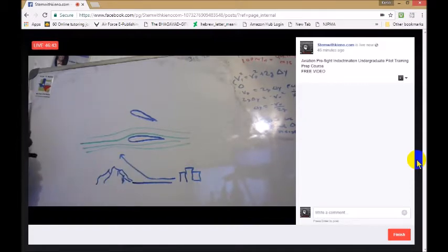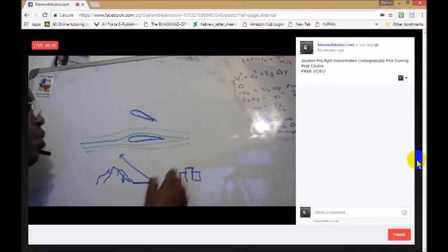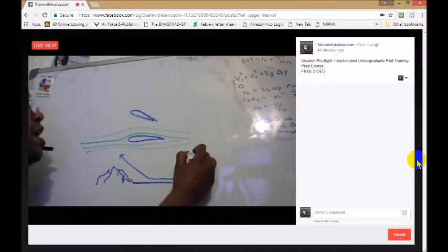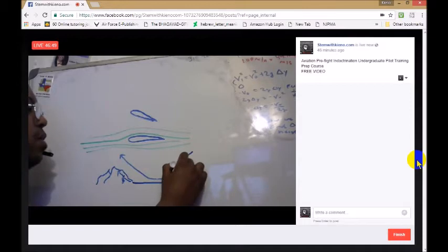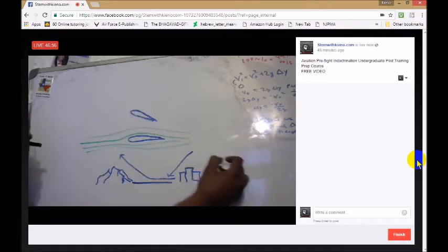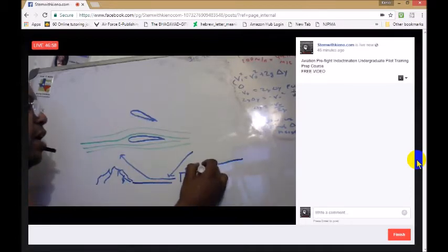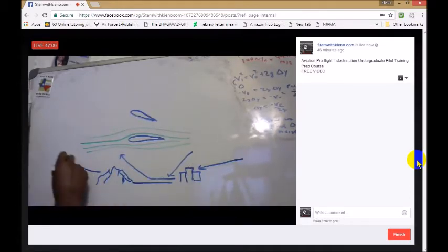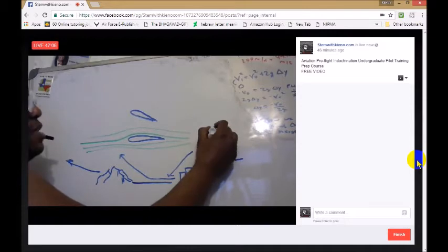Conversely, if we have obstacles at the approach end of the runway, we can come in at a steeper glide path without increasing our airspeed. So if we didn't have slats and flaps, we would need more of a takeoff and departure or approach and departure path like this. But when we extend our flaps and slats,